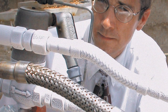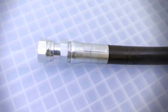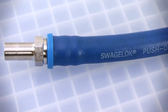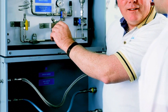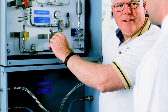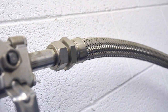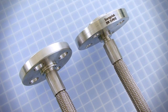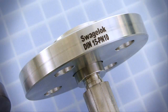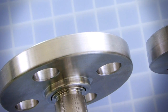Second, consider the hose type you have selected as it relates to compatibility and pressure and temperature ratings: metal, fluoropolymer, nylon, or rubber. Now consider the material and type of end connection in your system to which the hose is being connected. The material of the system and hose end connections are usually the same. Many types of end connections are similar in appearance but may have minor dimensional or thread differences based on regional requirements that are not interchangeable.